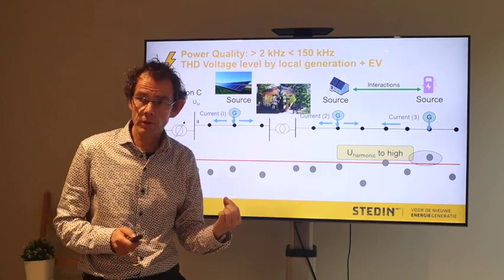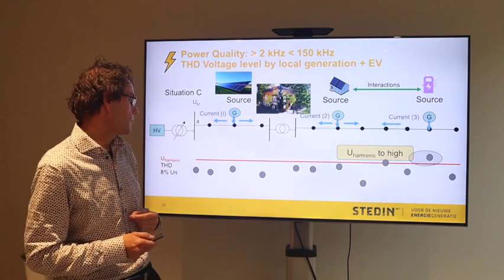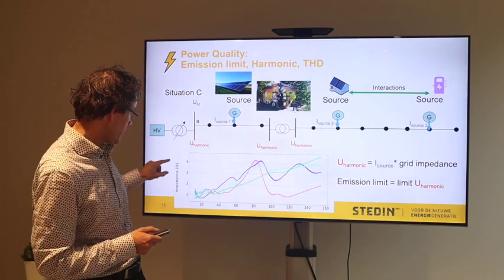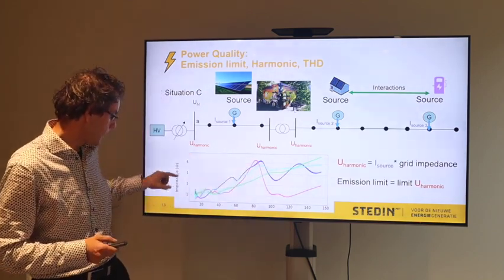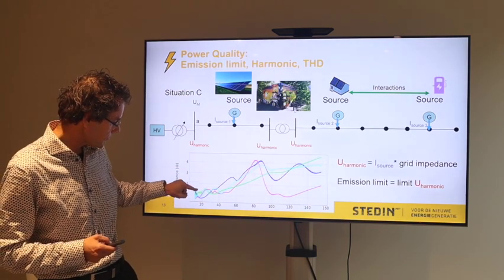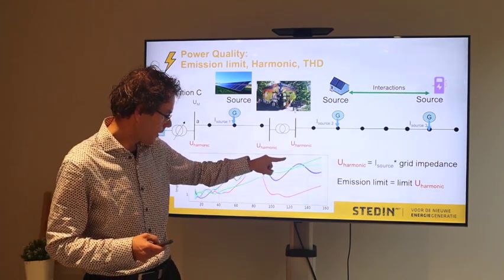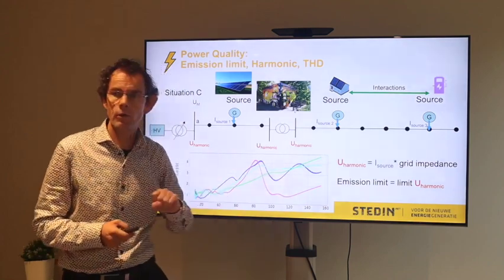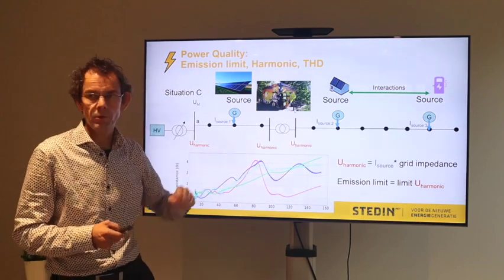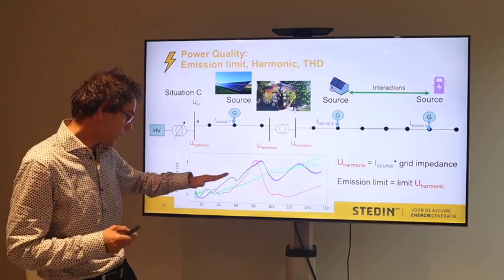It comes from the frequency going higher, and that makes another kind of impedance pattern, and that is what I want to show you now. So this is the impedance graph, and we're starting at 50 Hertz, the impedance of the grid, and you see the impedance really shows resonances. It's going up very high. So if the frequency goes up, the impedance will be higher, but it's not linear, there are some oscillations too. So we as an operator have to know about this impedance.